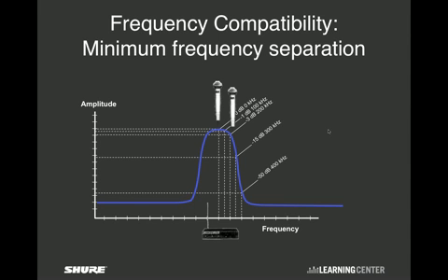But if we were to fire up another transmitter at 600.2 megahertz, the receiver would also be perfectly happy to pick up that transmitter, because the receiver's filtering is really only 3 dB less sensitive, 200 kilohertz off from its main frequency. So you probably wouldn't want your second transmitter tuned that close in frequency. But if you go up to 400 kilohertz apart, so 600.4 in this case, then it's perfectly fine, because now you're at the filter's 50 dB down point. That's far enough down that it's really not going to cause any issues with this receiver. Again, this would be on a pretty good system.